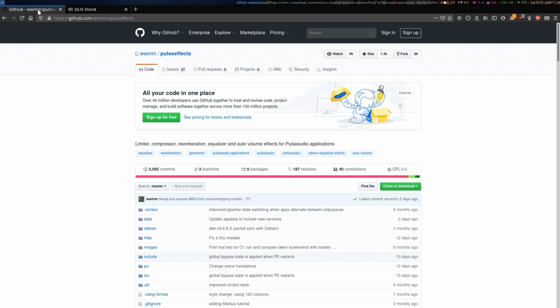A noise gate has been particularly useful for me because I'm often in a noisy environment with kids playing or with wind noise, but it's useful for other things too, like noisy keyboards, which can annoy some people too. What noise gates will do is suppress sounds below a certain threshold level that you can set, but then it allows sounds above that threshold level to go through untouched, such as when you start to talk. Now, I'm no audio engineer, but I'll try and share with you what I've learnt so far.